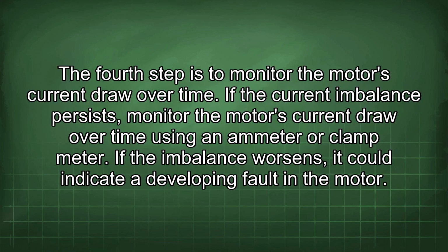The fourth step is to monitor the motor's current draw over time. If the current imbalance persists, monitor the motor's current draw over time using an ammeter or clamp meter. If the imbalance worsens, it could indicate a developing fault in the motor.